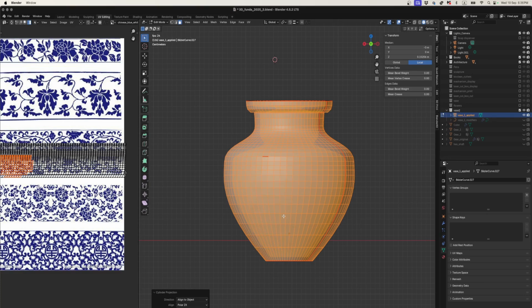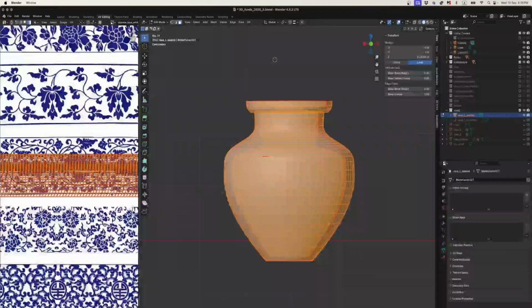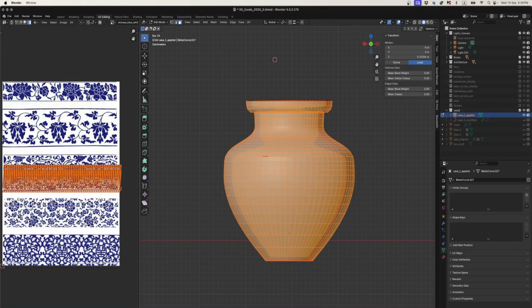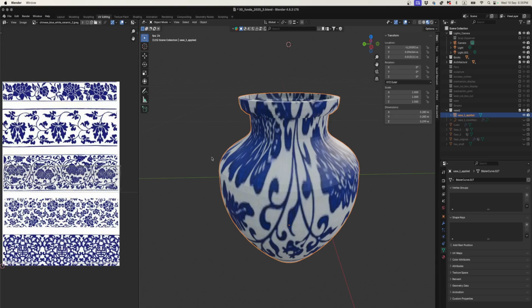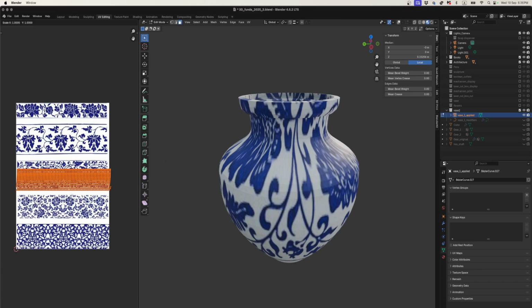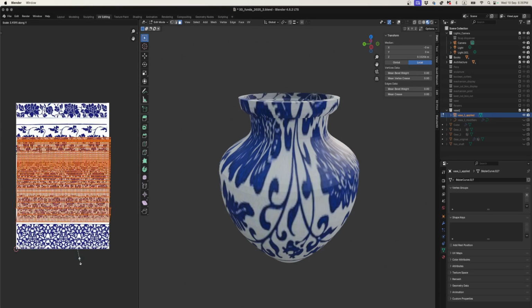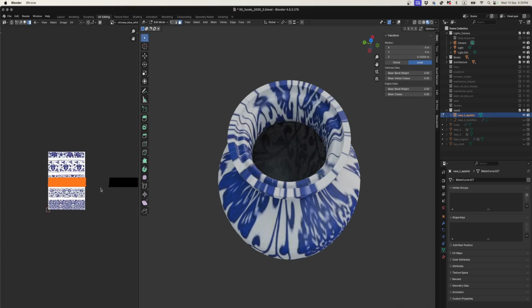Okay, so if I go into my cylinder projection and set it to align to object, we seem to get pretty much the type of UVs we're looking for, which is just this more or less rectangle of coordinates. Now if I go back into my material preview mode, go into edit mode, turn off my overlays, and scale Y, oh, looks like I didn't have everything selected. Hold on a moment. Okay, our UVs are overlapped here.